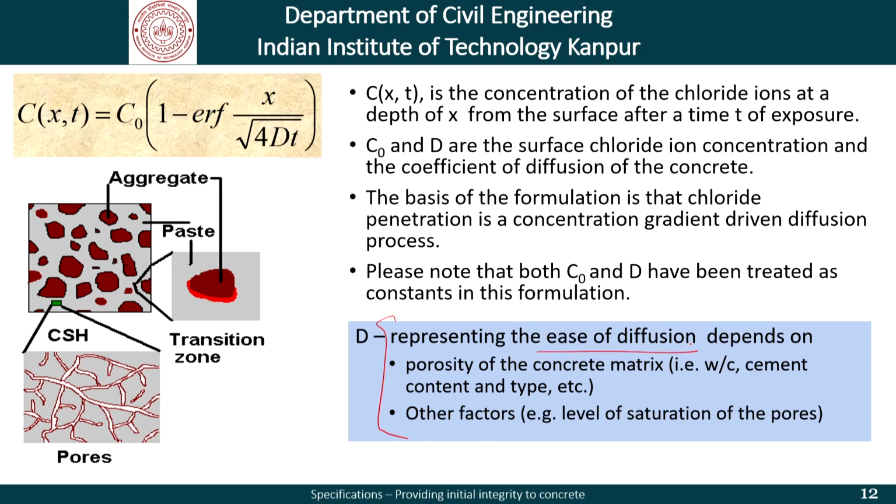Of course, it is the diffusion coefficient in mathematical terms, but basically it represents the ease of diffusion depending upon the porosity of the concrete mix, which in turn depends on the water cement ratio, the cement content and type, and other factors such as the level of saturation of the pores and so on.